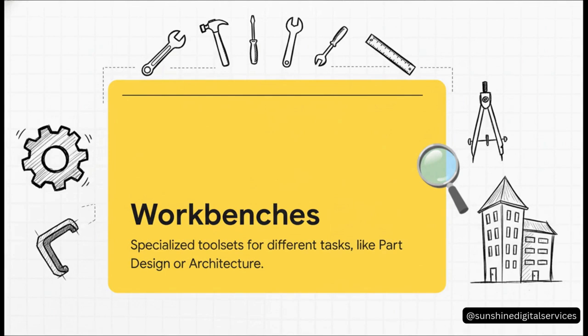The second big concept is workbenches. The best way to think about this is like a real workshop. FreeCAD organizes all its tools into these specialized sets. So if you're designing a mechanical part, you'll grab the tools from the part design workbench. If you're working on a building, you'll switch over to the architecture workbench. It keeps everything clean and organized, so you'll only see the tools you need for the job you're doing right now.